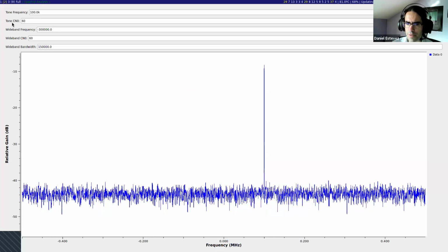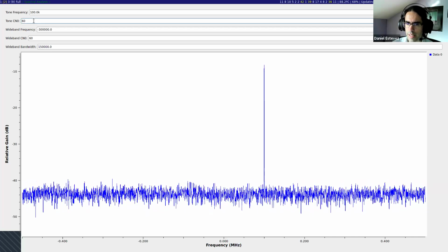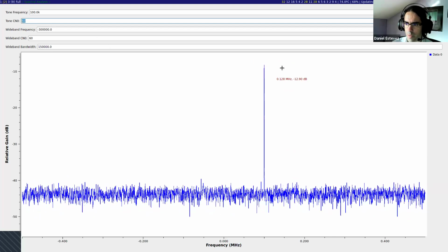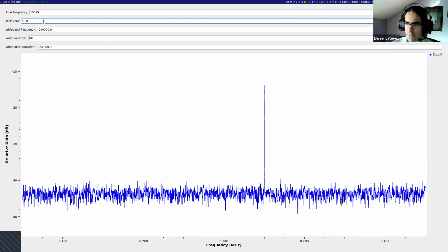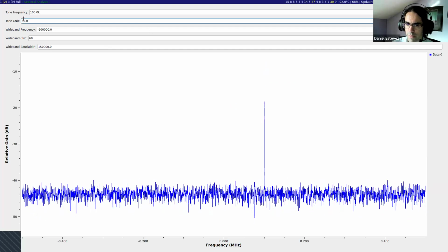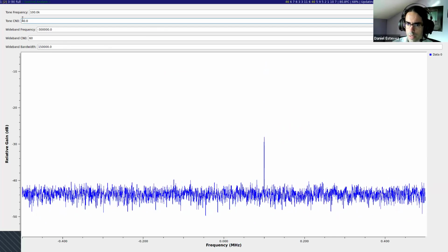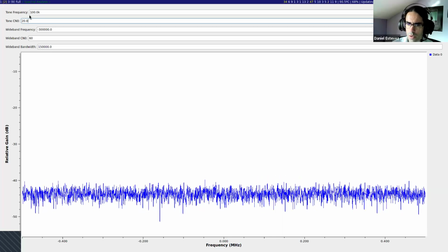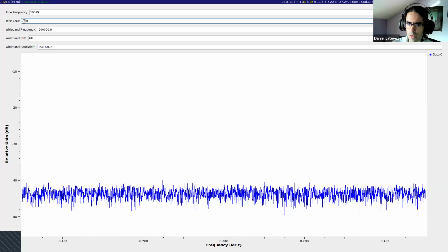And then I have something called CN0 here, which I will explain in a second. This is used to set the signal to noise ratio of the signal. At the moment it is set as 60, and I'm going to decrease it. I'm going to set it at 50. This is in decibels. So it has gone down by 10 decibels, 40 goes down by 10 decibels more. Maybe let's put 20. It goes down by 20 decibels more, and maybe I should set this to 25. Okay, maybe 30.